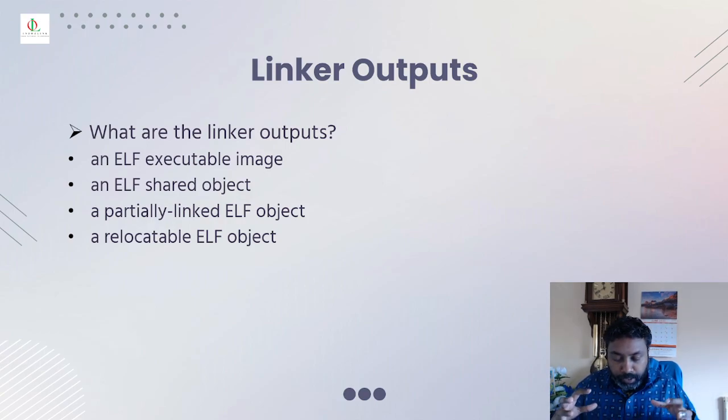Again, ELF stands for executable and linkable format. When you pass the compiled program to the linker, the linker script plays its role, where it declares its memory declarations and the sections, as we previously learned in the startup file about how you create your own sections. Likewise, the linker script will declare its own memory, where it is going to be placed inside the microcontroller memory, whether in flash memory or SRAM. It will also declare its sections, the start address and the end address, or where it has to be located. So that's where the linker comes in handy.